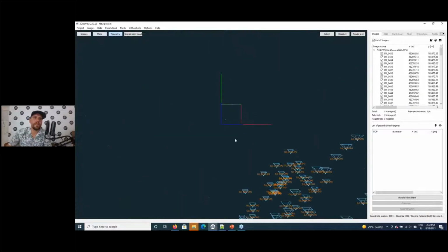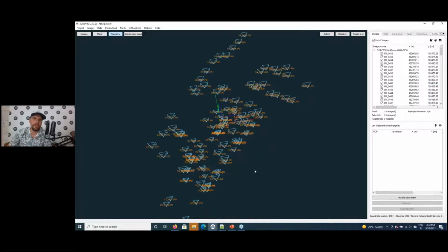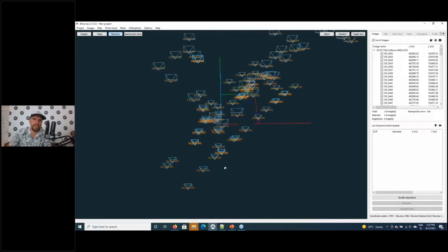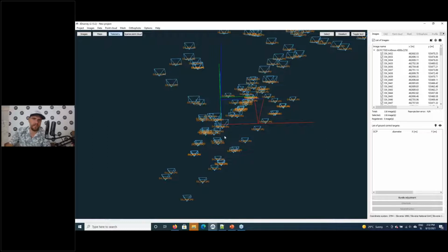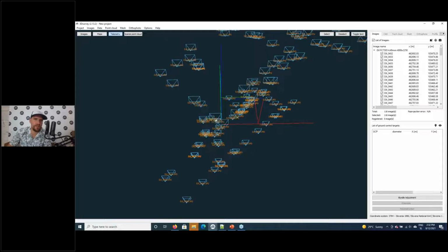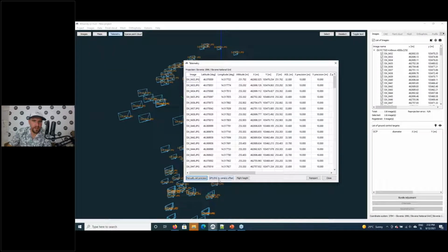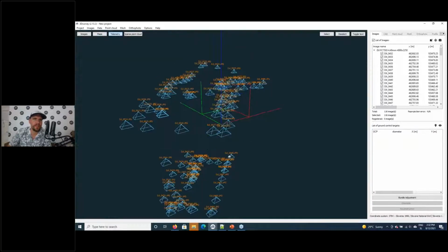Okay, first thing to note, if you plan on using DJI Mavic Mini drone, is this one is missing the camera orientation data. That's why all cameras are pointing towards north. If you get this kind of data, you can easily fix it by going to data, telemetry, INS to camera offset, and we will just rotate all the cameras by -90 degrees. Press confirm, close, go to telemetry view again.